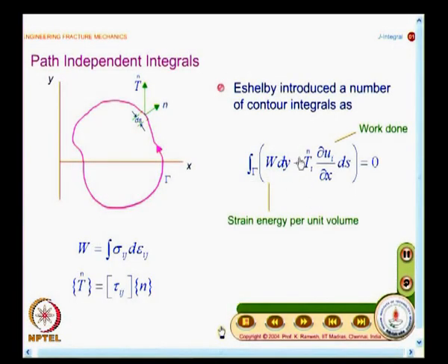And if you look at the second term, this is written in indical notation. So, I have T i multiplied by dou u i divided by dou x. So, this will repeat. If you look at the Einstein summation convention, when I have i, this indicates that this would repeat. Since we are considering a planar situation, you will have the first index 1 and second index as 2.